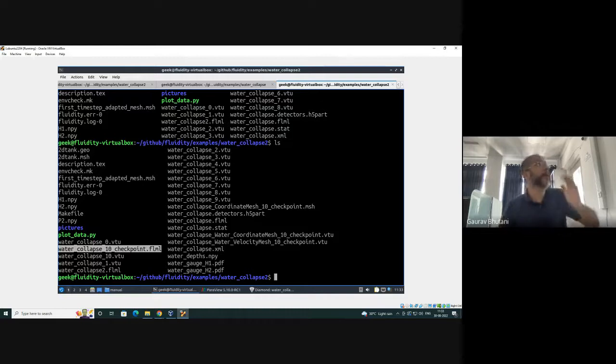FLML is the one that we used to initialize. So rather than running the initial FLML, which initialized everything from 0, you can run this FLML, and automatically it starts from that point. There's nothing else that you need, everything is set there. You simply need to write fluidity followed by this checkpoint file.flml, and it will run. That's the good thing about creating checkpoints.